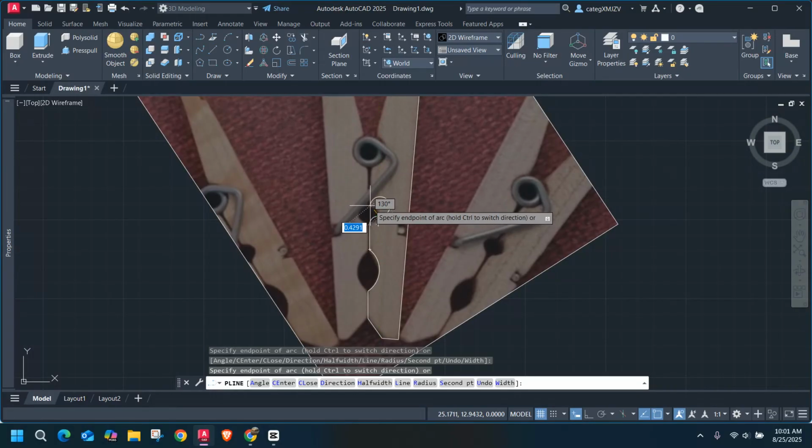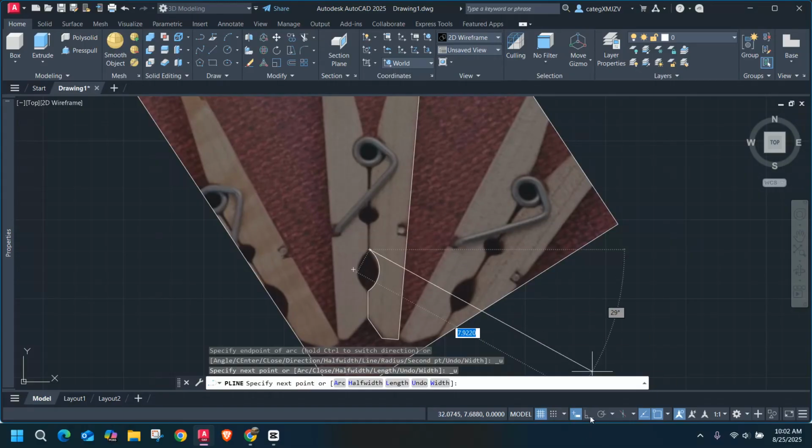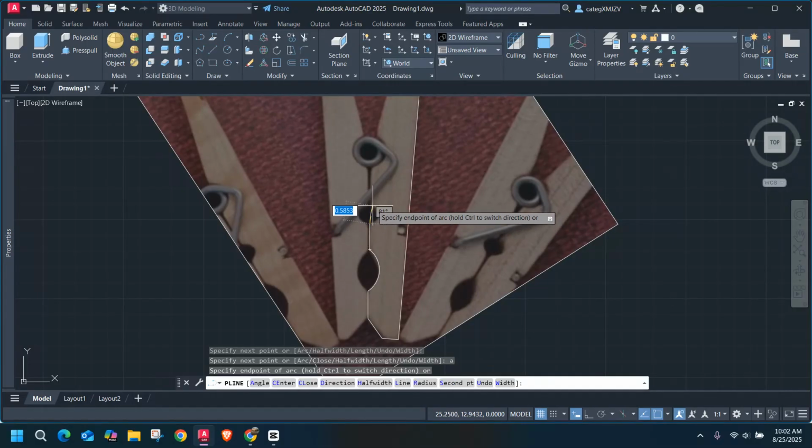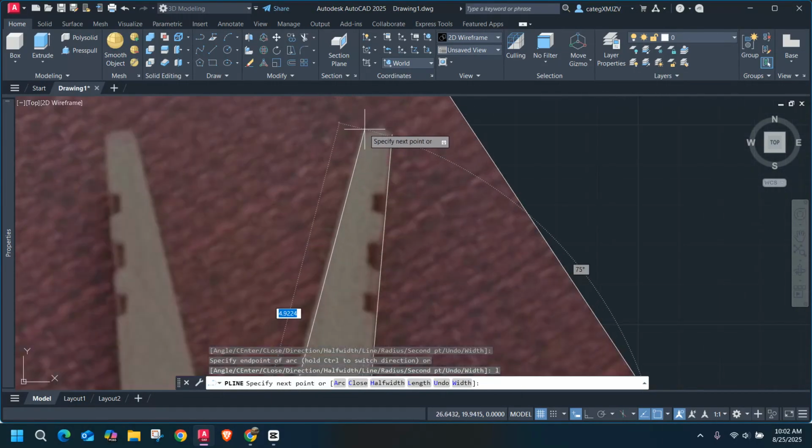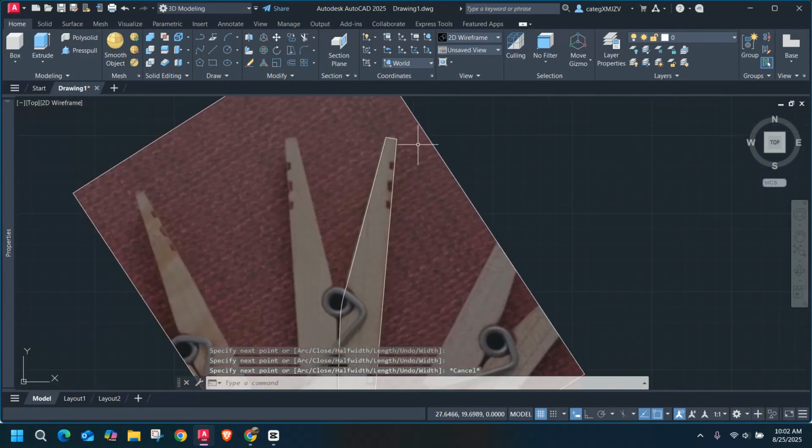And the nice thing about it, let me go back so I can show you, is you can manipulate it. So say I choose to do my arc to here. It looks like it's a straight line. Go back to my line, straight, arc from here to here, okay? Then I go back to a straight line and just use L, up, and then I'm going to close it, okay?